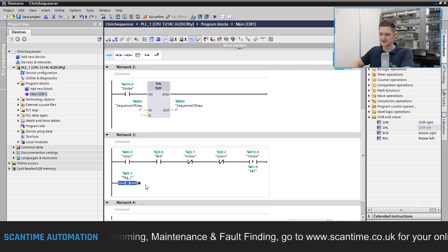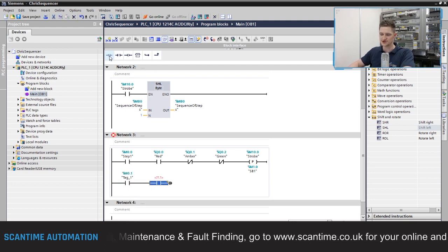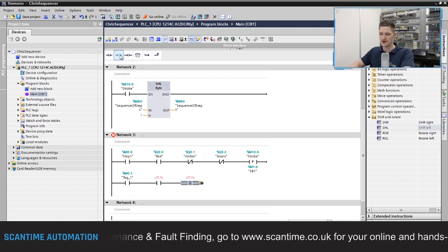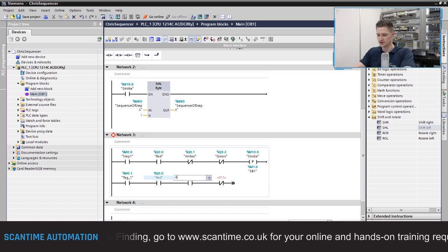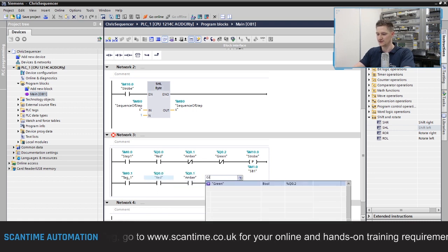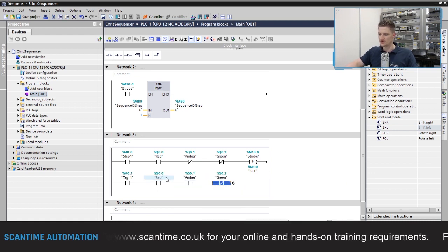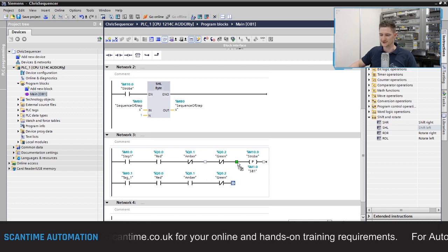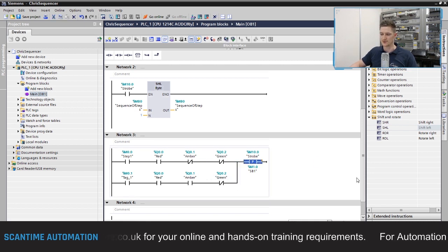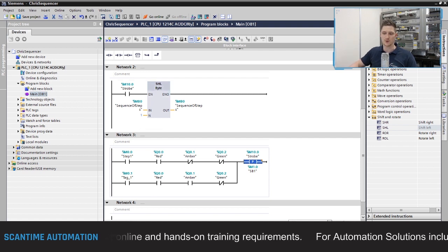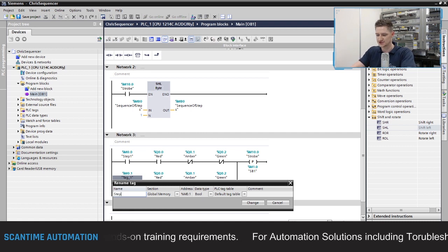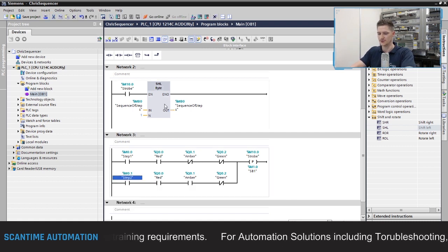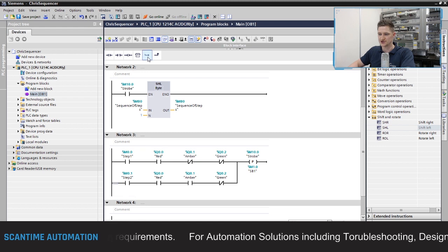is then going to wait until the red lamp is on, the amber lamp is on, and the green lamp is off. So when the red is on, the amber is on, and the green lamp is off, that then is when that step is completed. So I'm just going to drag that up, and that will then trigger the strobe signal again for one PLC scan, shifting the bit one place to the left, which will then turn on step 3. I'll just rename this step, step 2. There we go. And then we'll start on step 3.